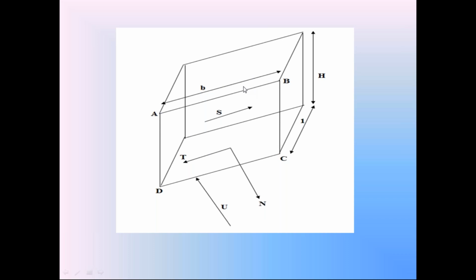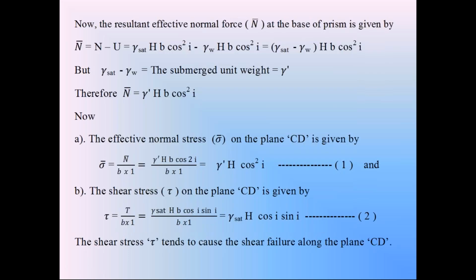So we are going to discuss the stability of this soil slope in the steady seepage condition by considering total normal force N, the pore water force U, and also tangential force T, and by taking the shear strength of soil S. So check that calculation of factor of safety in the third case carefully.